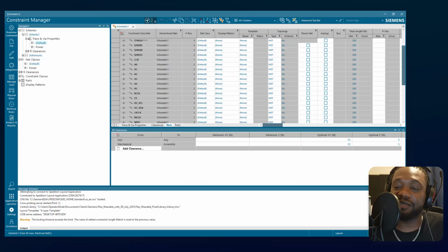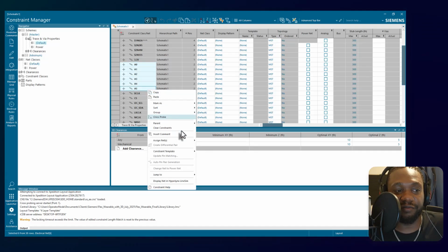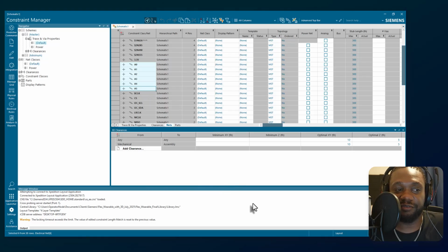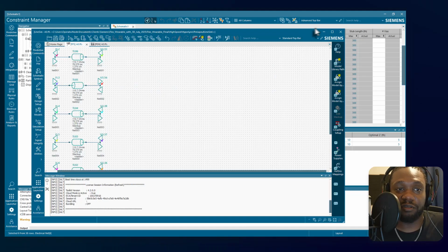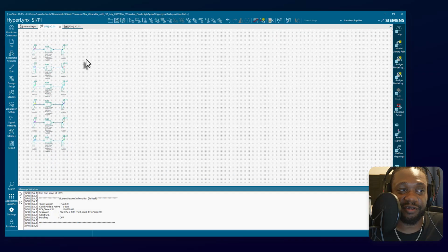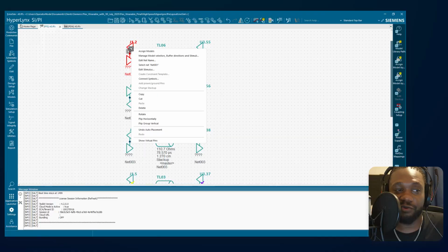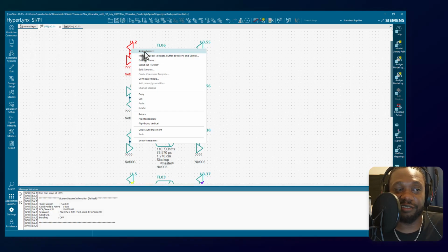Once I handle signal integrity analysis, we'll get a bit into routing. So for signal integrity, what you can do is select any of your nets, right click on any of them, and then open up the display net and HyperLynx line sim feature. This is only applicable or possible with the add-on. You just install the add-on tools. So HyperLynx gets popped up. This is HyperLynx Signal Integrity Power Integrity tool. And look at that. We have our signals doing their thing. You can right click on these transmitters and receivers and assign specific models, manage model selectors, buffer directions, the stimuli.